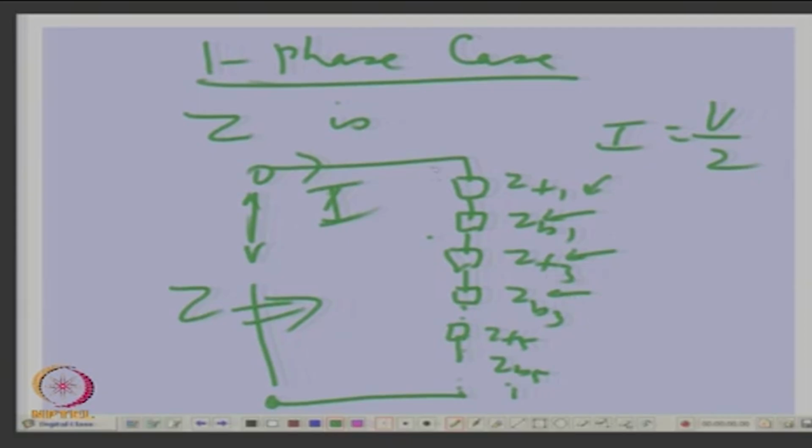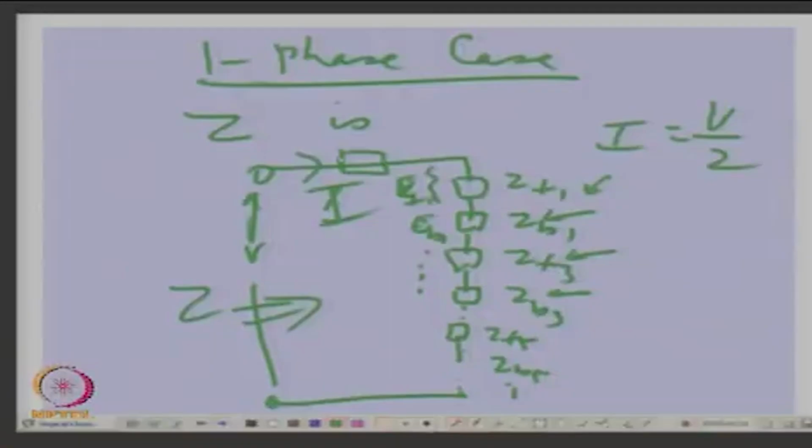They are all inducing some voltages, say EF1, EB1, like that, because in the air gap there are fields, it will induce voltage in that winding. So, we have a net impedance which will have a leakage impedance ZL plus all these harmonics. Is it clear now?